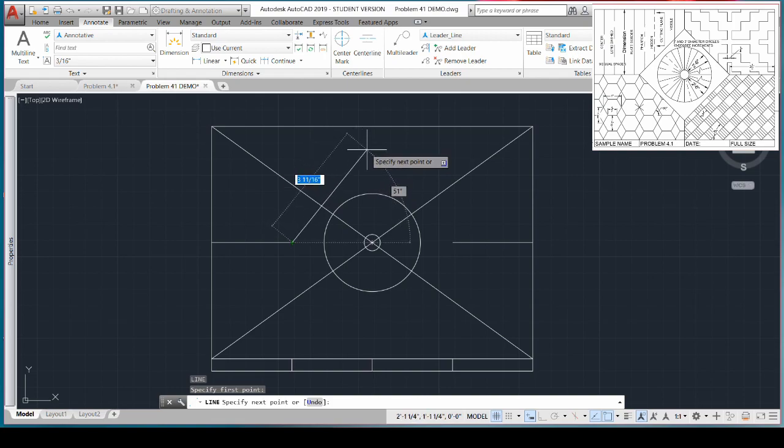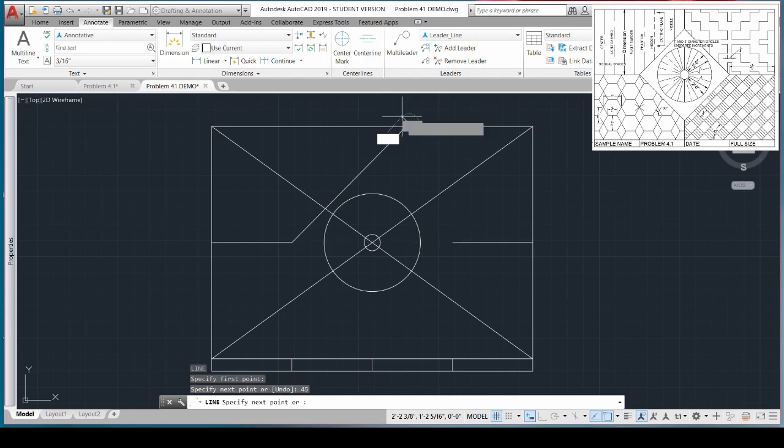So I could do that by just drawing a line up and then hitting tab to move the cursor over to enter an angle, 45, enter. And then enter again. And then I want to draw the other side, so enter again for another line, the end point on the other side, and then I want to do perpendicular.